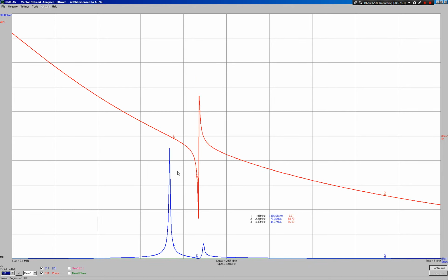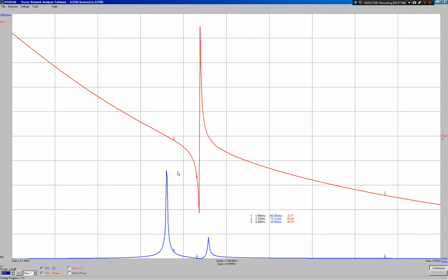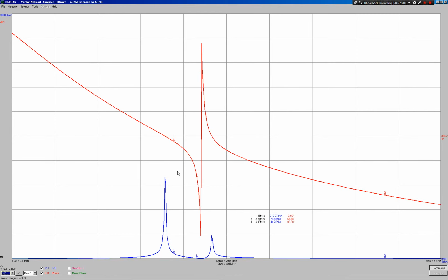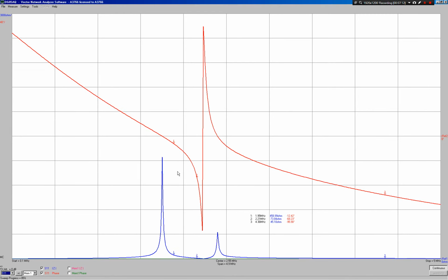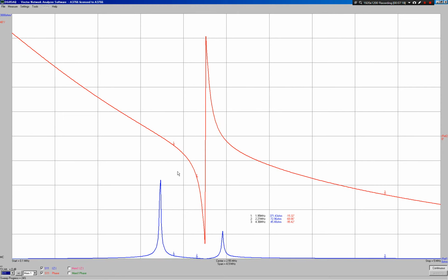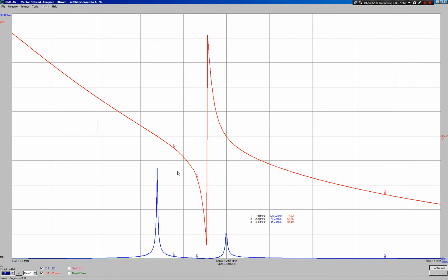Keep bringing it in closer. Phase change becoming strong now. You see the splitting, forming the lower and the upper resonant frequencies very clearly. Okay, that coupling coefficient now is probably between 0.1 and 0.2. They are now separated by only 5 centimeters. Bringing them further so they become fully interlocked.